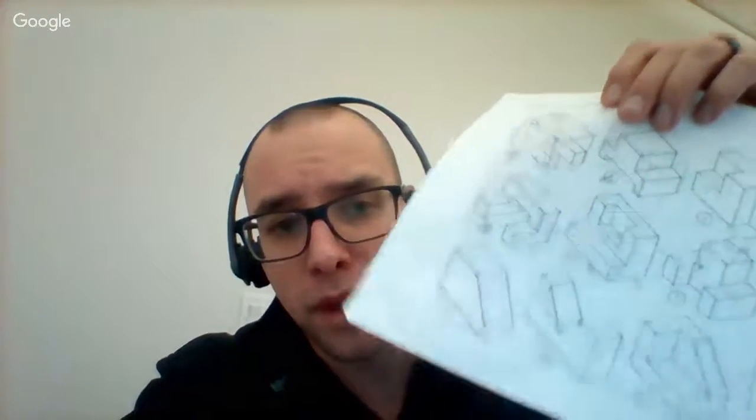We're doing more Inventor. I'm going to finish up our first assignment here. Remember, I keep saying it, I'm going to keep saying it: start on paper. Figure out your overall construction box. That construction box is really important, and it helps you go through and model everything, and you get all your measurements down before you even get started, and it makes your life a lot easier.